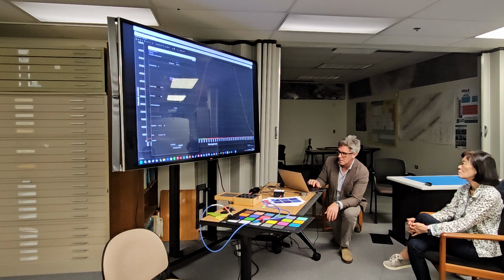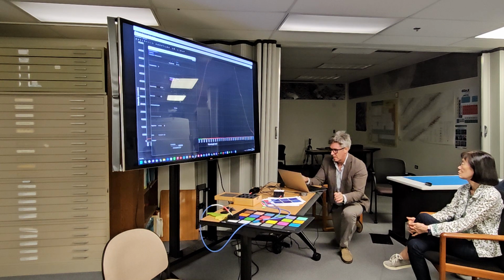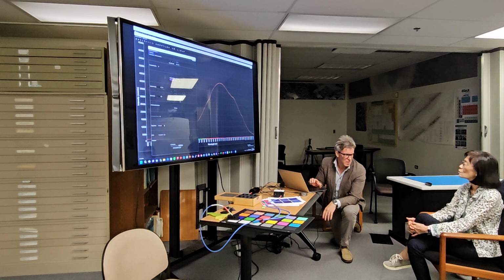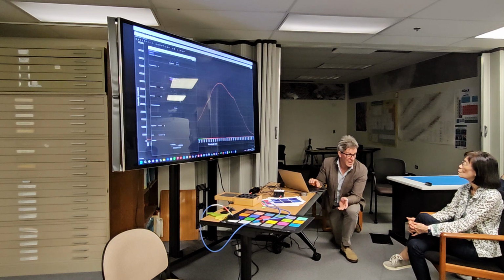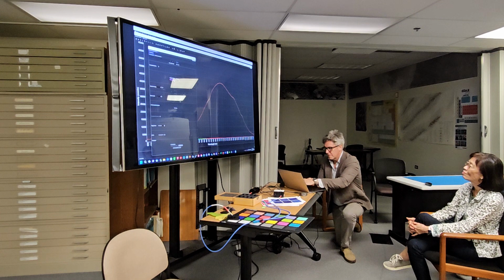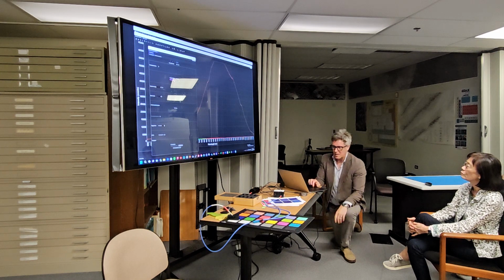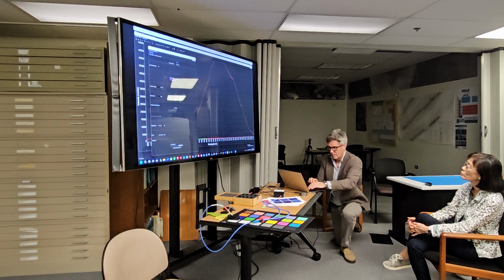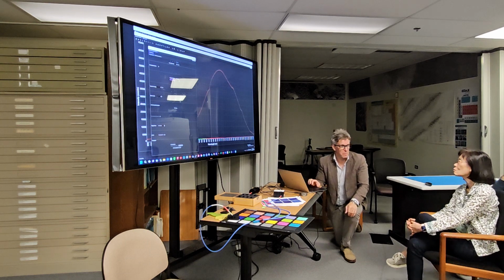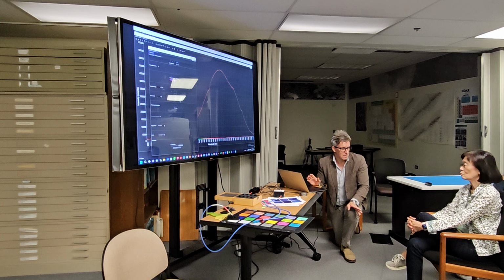So 100 gives me that. But here I'm sacrificing signal, right, on some level. I really want to collect as many photons as I can to give myself a higher signal to noise ratio. So I don't want to leave photons on the table, so to speak. So, you know, I could just play with that. I could make 150. Yeah, I still got some saturation. 125, split the difference. Not bad, right? So now I'm using most of my dynamic range, right?